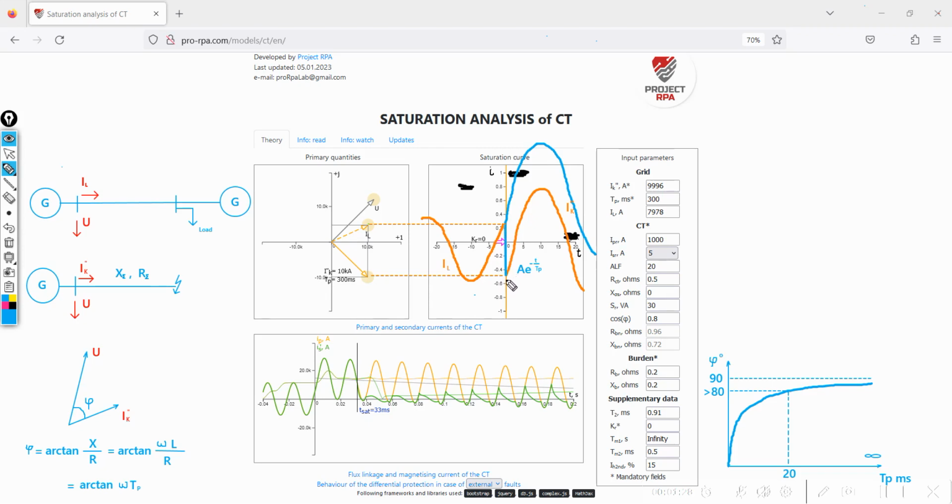In the case of networks with inductive components, for instance a power line or a transformer, a sudden jump of the current is not possible. However, the jump doesn't occur because it gets compensated by the so-called DC offset. This magnitude here is the DC offset. It can be expressed by this e-function, where A is this magnitude in the graph, the initial value of the DC offset.